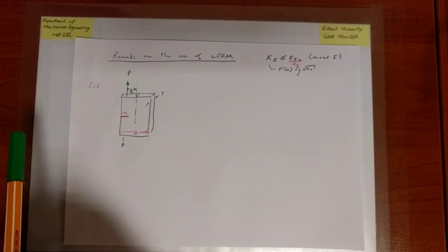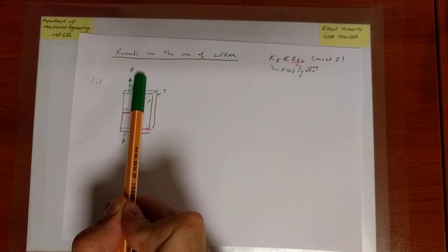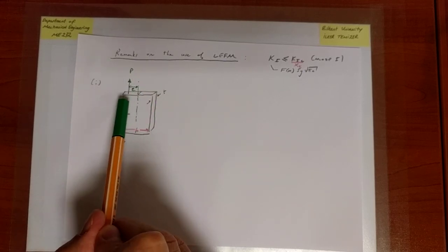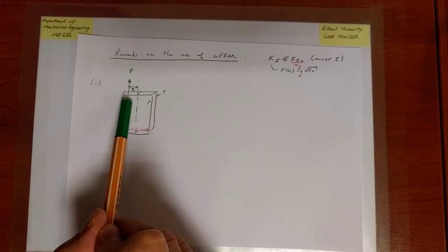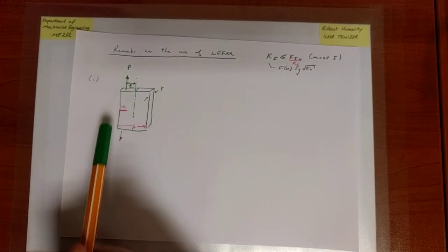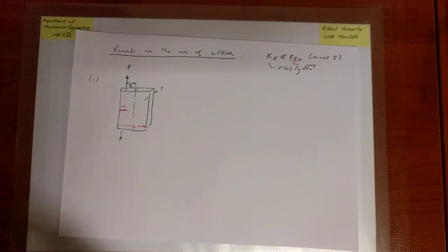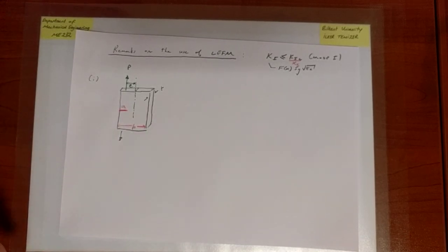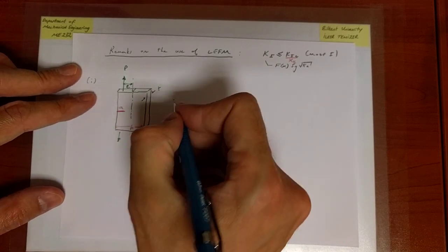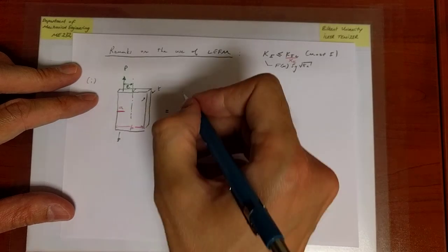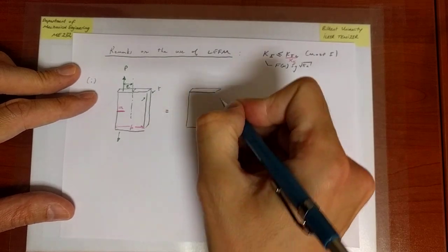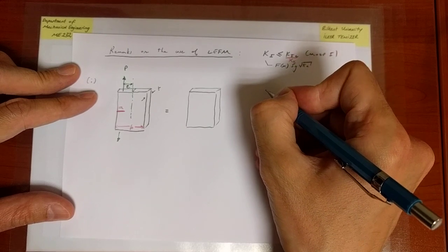However, if we do an offset, there will be some tensile force in addition to bending applied with respect to the central axis. Or, stated another way, the stress field at the cross section where the crack is present, omitting the presence of the crack, is not going to be uniform. There's going to be some bending stresses, so there's going to be some distribution of the stress, which is far from being a constant. So that's a case that looks slightly more complicated because it doesn't seem to be a scenario that we've actually looked at, but in fact it is a case that we have looked at. And the way we are going to address this scenario is by decomposing the problem into two individual parts. In the first part, we're going to take the same geometry. In fact, we're going to take the same geometry once again in the second part.